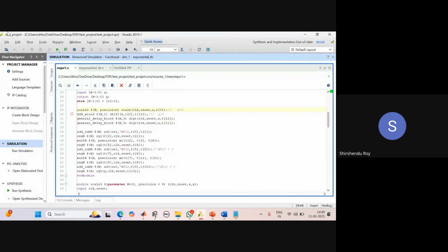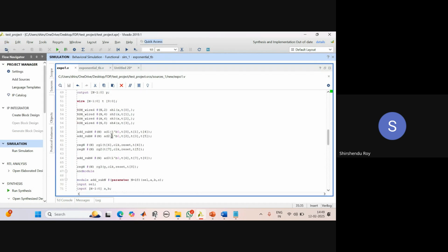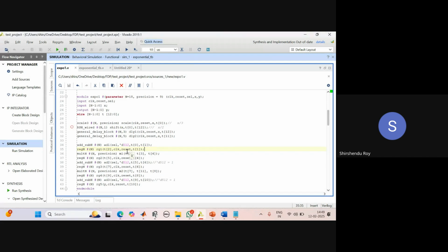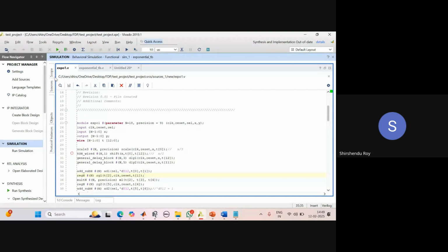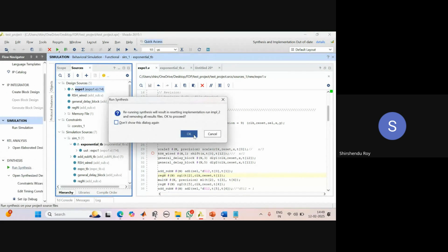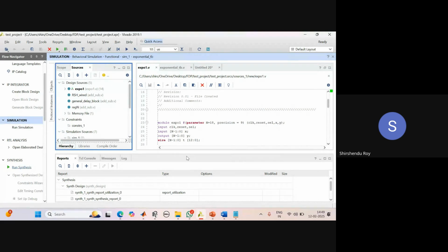Okay, now the better way to understand what is the error we have done. Sometimes we are not understanding that it looks no problem in the scale block, but it may have some problem in the main design as well. So to understand that, I will select this block as a top module and synthesize this block. Better understanding can be done by synthesizing again and again. There will be some issues, warnings or errors it will show, and based on that, I can also find the error.